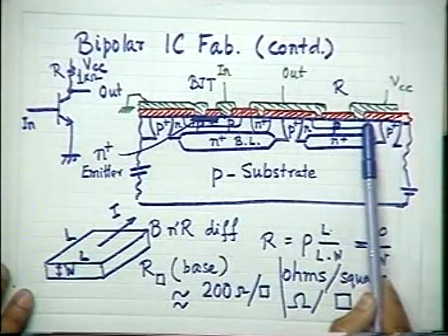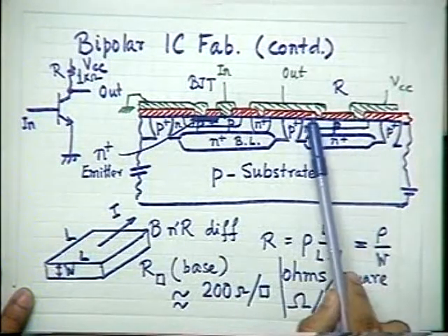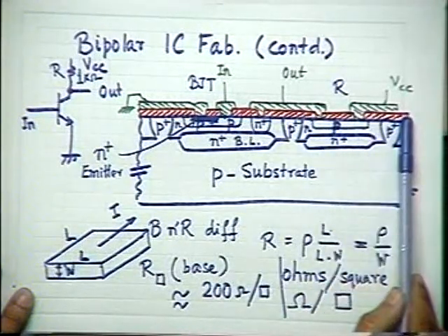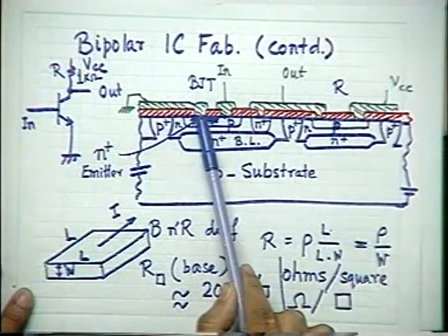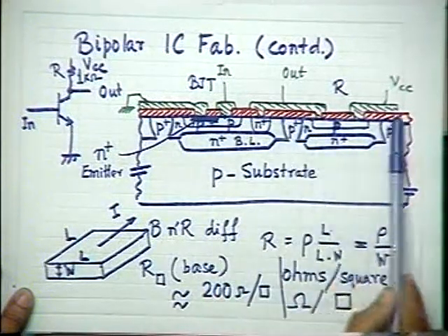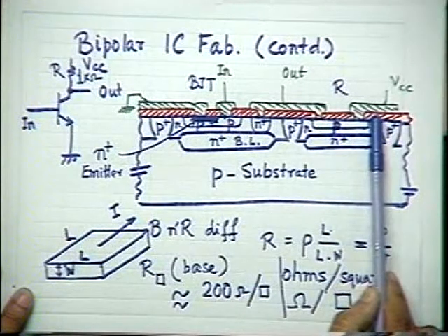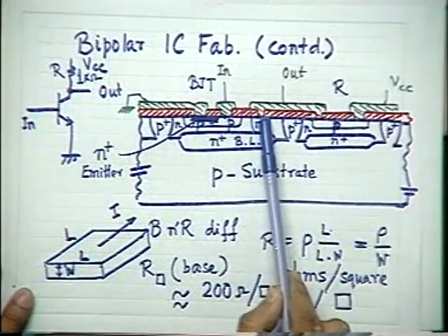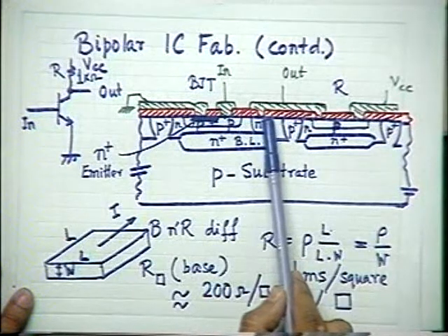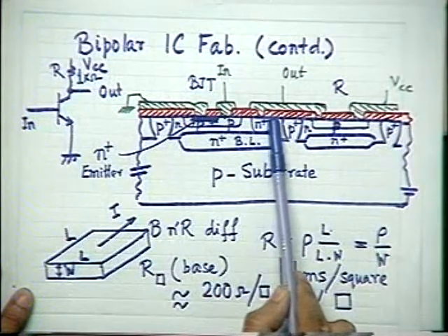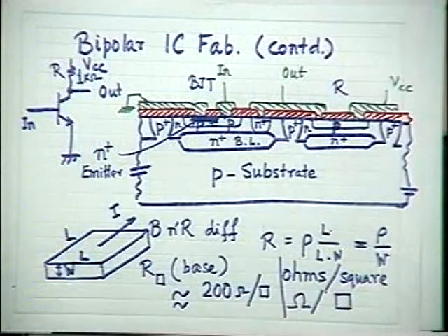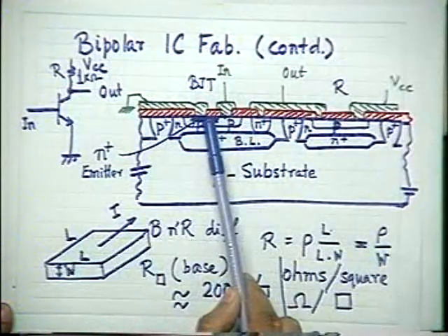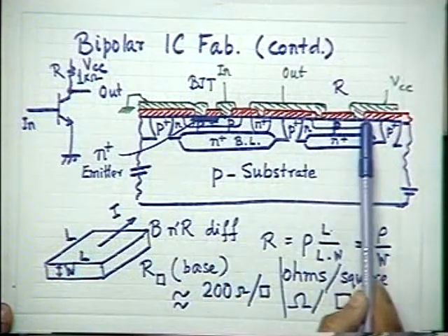So what I will do? I keep it covered till the emitter diffusion window is open. I keep this whole thing covered by oxide till the windows for emitter and collector contact diffusions are opened. Then, along with the collector contact and emitter diffusion, I also open the window in this region.